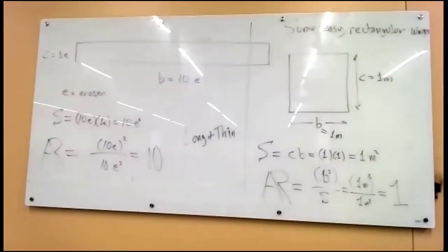You're in senior design, and you're doing aerodynamics. And you go to your structures guy, and we'll find out that how efficient the wing is directly related to the aspect ratio. The longer and thinner it is, the more efficient the wing can be. You go to your structures guy who has to build this thing, and you go, I want to build a wing that has an aspect ratio of 100 because it gives me the best lift. What do you think about that? It doesn't look like we could actually do that, right?